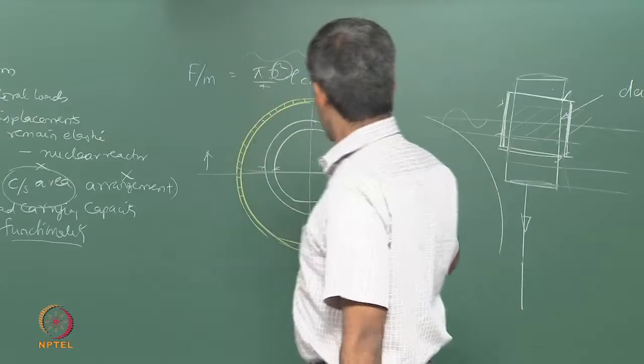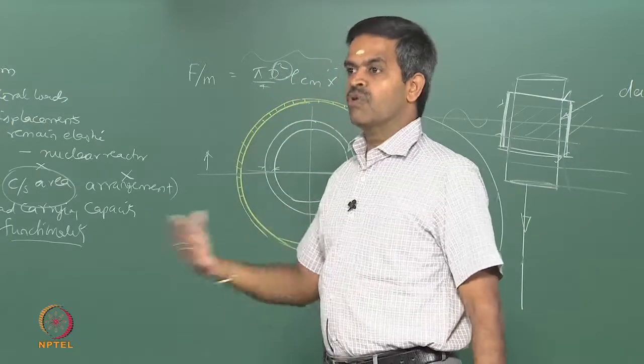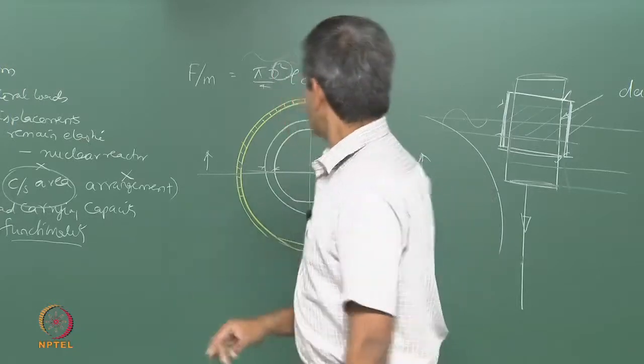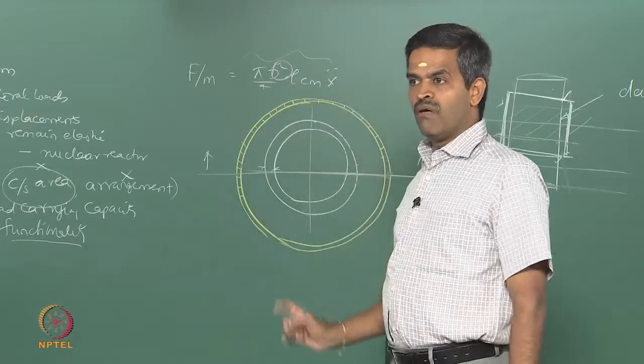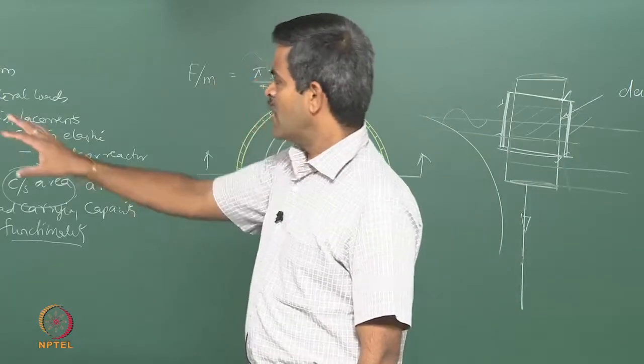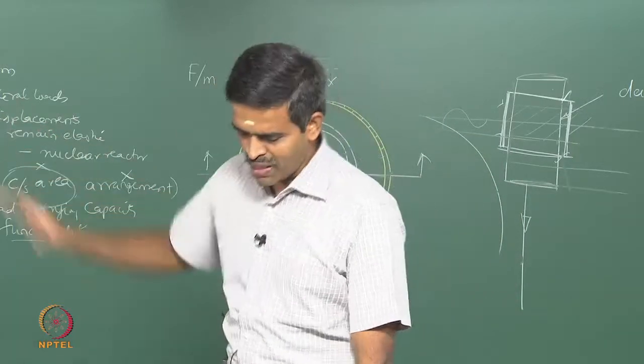So, if the external cylinder is damaged in due course of time because of corrosion effects etc., we can keep on replacing them without bothering much about the inner member, which is the original part of the structural system. That is the idea here. So, the main advantage is reduction of hydrodynamic force, people have already verified this.